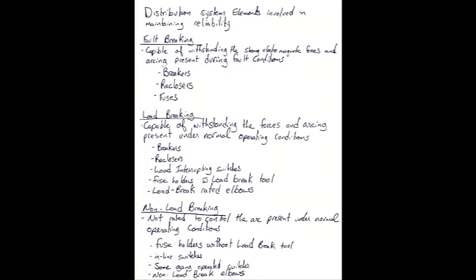These tools have no means to address the arc that is going to be drawn out. And so if you open one of these switches, you're creating an arc, and then that arc is going to be uncontrolled. And who knows where it's going to go or what it's going to get into. And if it finds its way over to another conductive surface, now you've got an arc established. And we saw in our video last week that was bad, right? And it's a self-inflicted wound, right? We did it to ourselves.